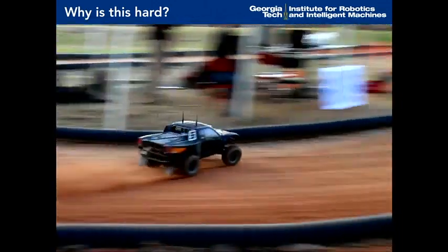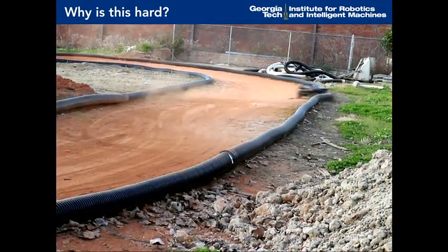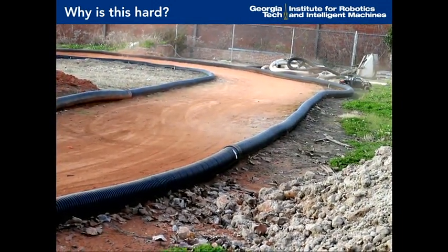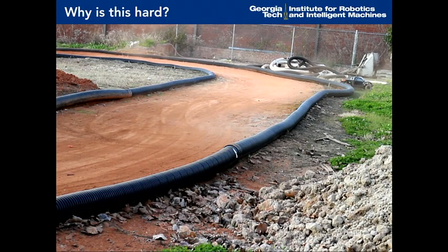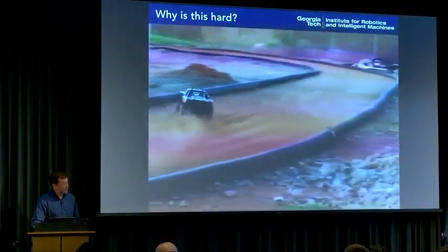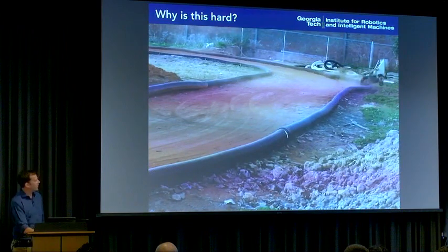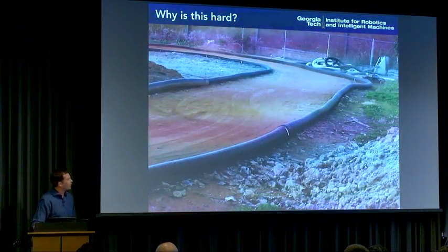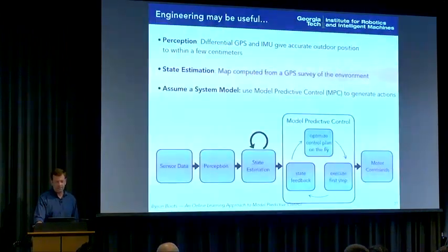And if you get the dynamics wrong, or have a policy which even makes a small mistake, then you're in serious trouble. The problem here is that the errors in your predictions compound, and they cause the car to generate bad behavior. So what you're seeing here is the car oversteering, and at fairly high speeds, this can be fatal for the vehicle.